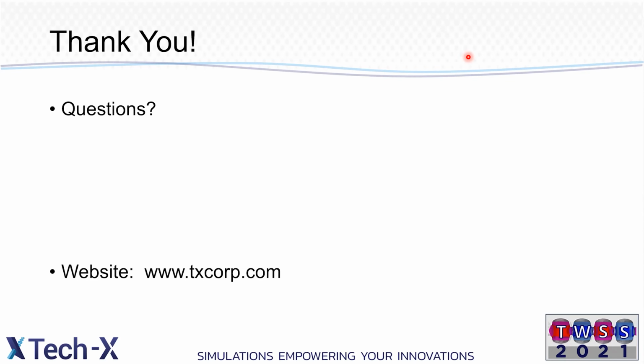Is there a way to couple the plasma wave into a free space terahertz wave? So we have played around with these meander line structures, specifically either to couple to a free space wave or to couple to a probe for modeling. The idea is that you can couple a strip line to the meander line pretty easily. And so then if you can couple the meander line to the 2DEG, then you've got your coupling. And then for vacuum, of course, you'd want to couple that strip line into some kind of radiating antenna structure. So there's a number of steps, but the long answer is yes.